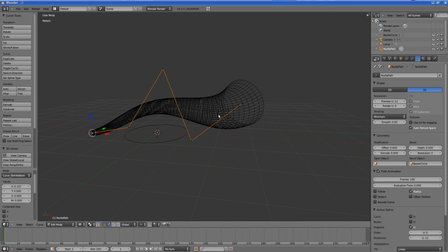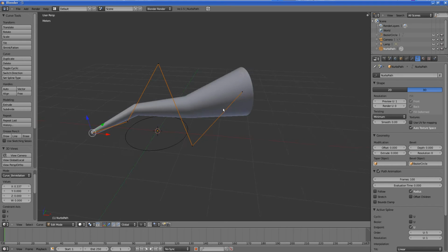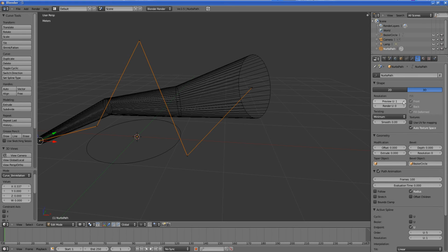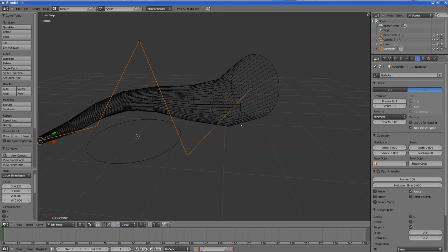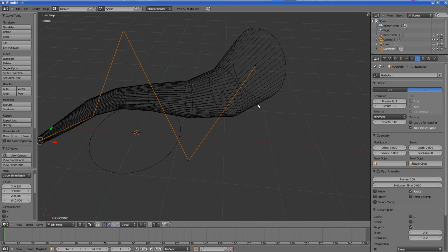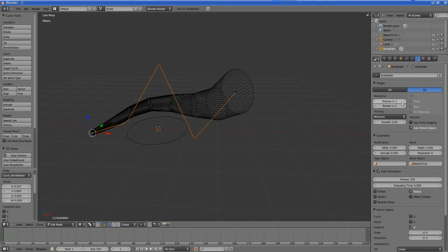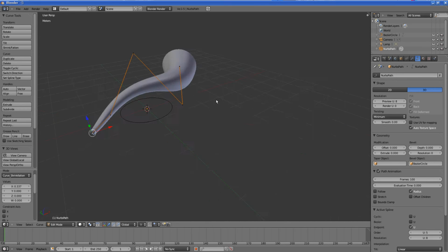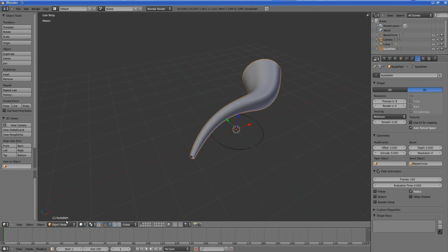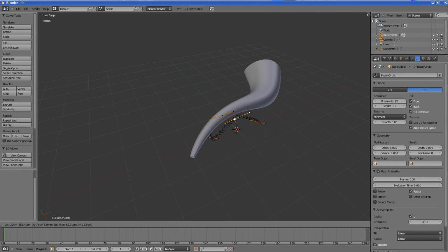Let's switch to the wireframe mode. You'll notice we have around 12 subdivisions in this direction. So basically between this vertex and this vertex, this controls how many subdivisions happen. Between this vertex and this vertex I have two subdivisions, like 1 and 2. So I can control the smoothness of this one, and I can go back to this object and move its vertices to control.